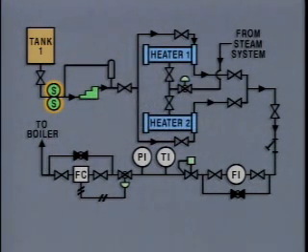From the strainer, the fuel oil flows to a positive displacement pump. There's a pressure relief valve at the pump discharge. The relief valve routes oil back to the suction side of the pump through this line if the pressure on the discharge side of the pump gets too high. This symbol represents a gate valve that can be used to isolate the pump and the tank from the rest of the system. From there, the oil piping goes to the next major components.